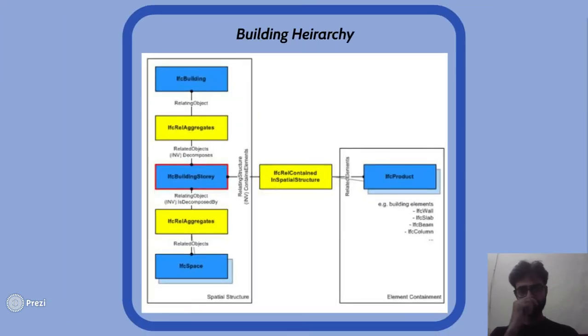Next, IFC also describes a building hierarchy, like the IFC building we have, then we have the IFC rel aggregates, how the buildings are grouped, and IFC space, IFC rel containing spatial structure, how the building elements, walls, slabs are grouped.